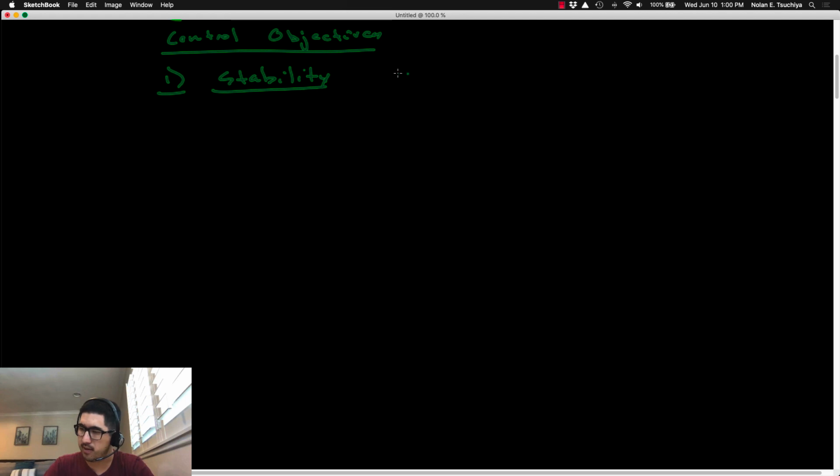However, remember that in the open loop sense, what we talked about last lecture was basically this. A system is considered stable, like the plant is considered stable, if you apply an impulsive input, like a delta impulse function, and your output converges to zero. Right? That was a fundamental definition of stability. So you have some dynamic system, you ping it with a hammer. Does the output eventually converge to zero? If yes, that system is stable.